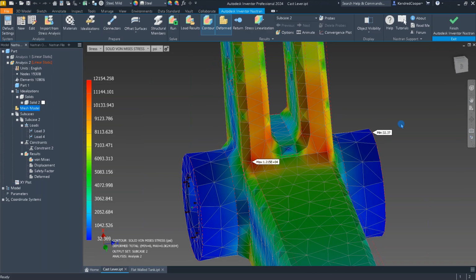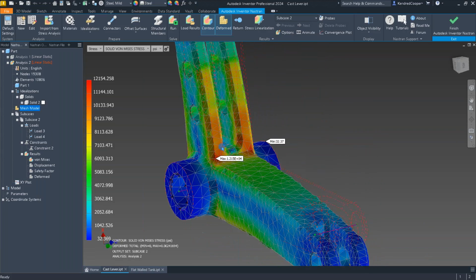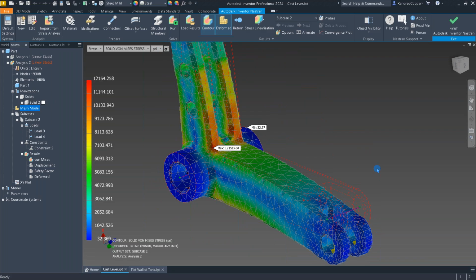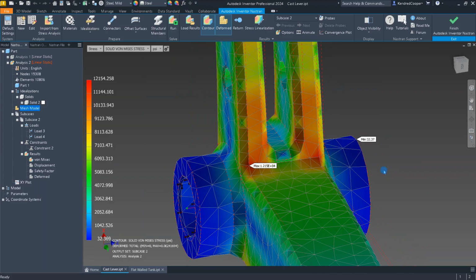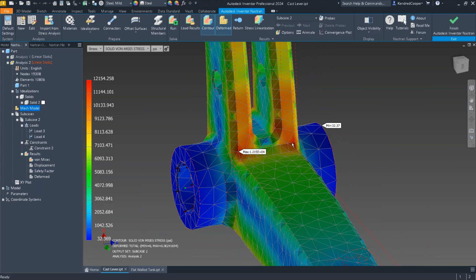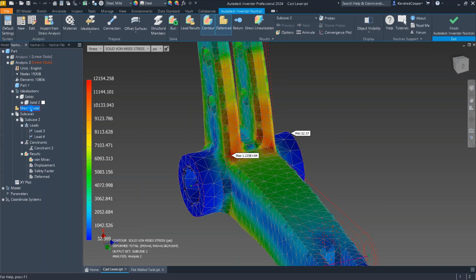And what you may notice is the stress area, the highest amount, might move around a little bit, might float from one fork to the other. It may move up and down a little bit, but it's staying in the same basic neighborhood. And that's what you want to see. You don't want to see that stress suddenly shoot out here to an area that shouldn't be under stress. When that happens, go back to your calculations and your setup. Something is off somewhere. So in this situation, our stress is staying in the same neighborhood. I think the first one is actually over here on the right-hand fork. Now it's moved over to the left-hand. So we've been making some global mesh refinements.